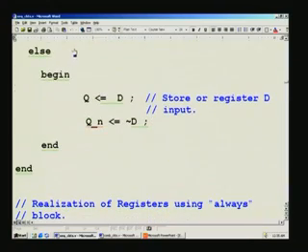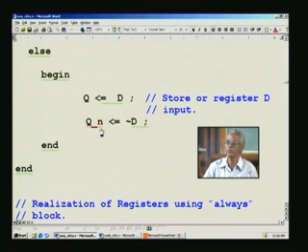And then in the course of normal working of the D flip flop, you just assign whatever is in D input to Q, and inverted D to Q underscore n. But unfortunately this creates two flip flops as such when you look into the synthesis tool later on. So, a way out to decrease the count is to put this as an assign statement outside, and have the same result, only an inverter will be used. That may be a better approach.